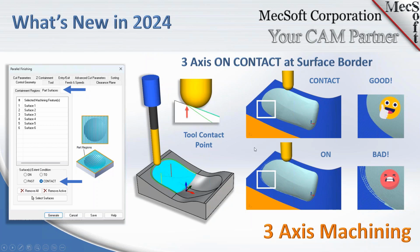And then starts going in the reverse direction, opposite that direction. If you look in these simulations, you'll see that down below in previous versions, the tool was riding up on the parting line and actually messing up the parting line. And you would see that in your actual molded parts, which is not good.